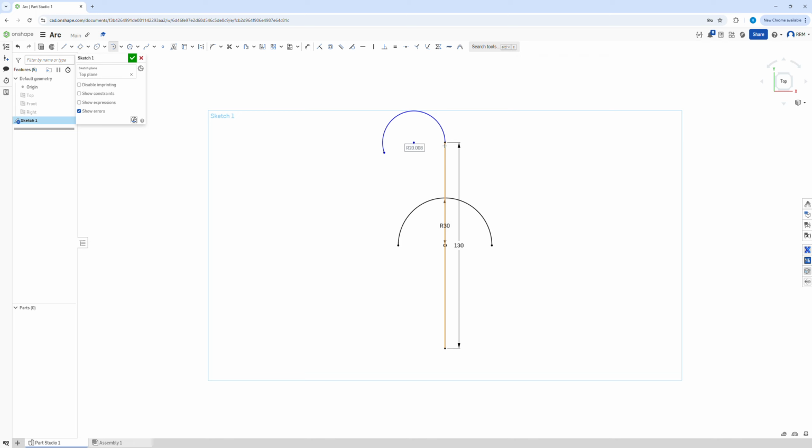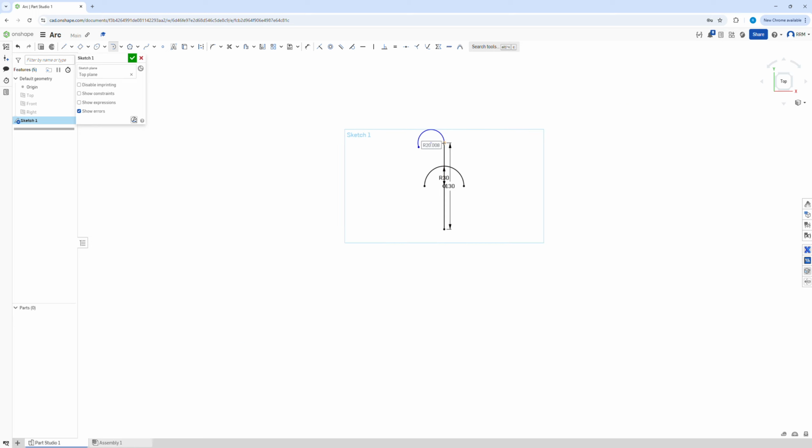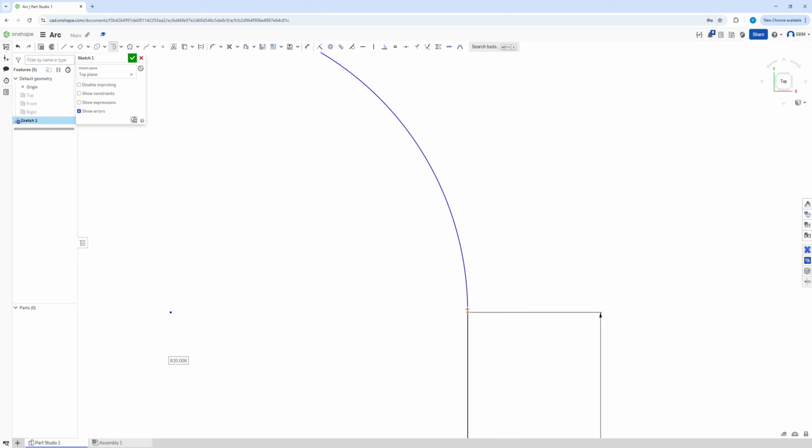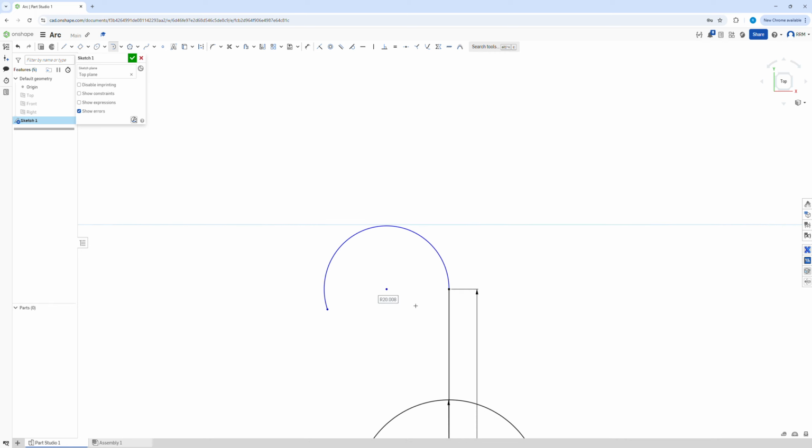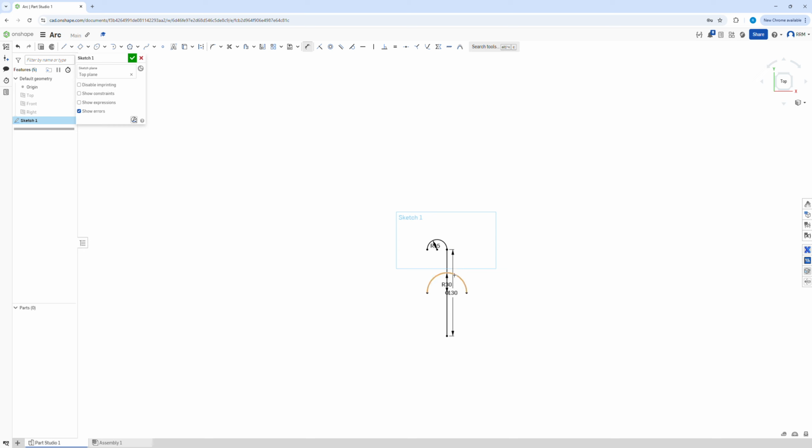Tangent means drawing the straight line, it's going to start in a perfect position in terms of vertically, and then it's going to curve off. So you have a feature that has a really smooth intersect here. If I was to just do a normal arc off there, it could go off at a random angle, which is not good. So again, we can get this constrained. So potentially, I want to do exactly the same thing, and I'm going to make these two here horizontal. And the only thing that can happen now, so if you think about it, it can go side to side. So maybe we want to get the dimension and dimension this radius, and let's make it 15. And now we have a fully dimensioned tangent arc.